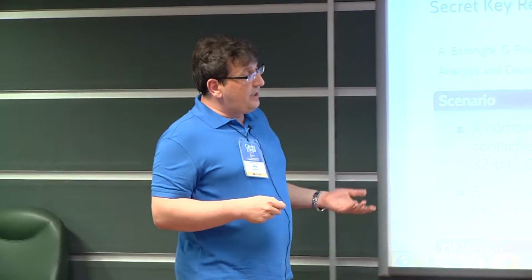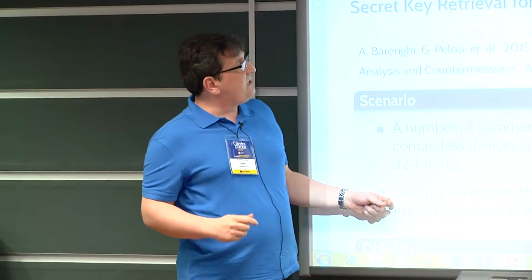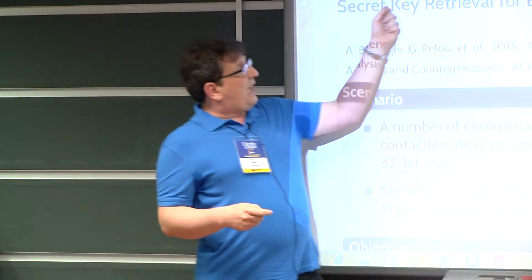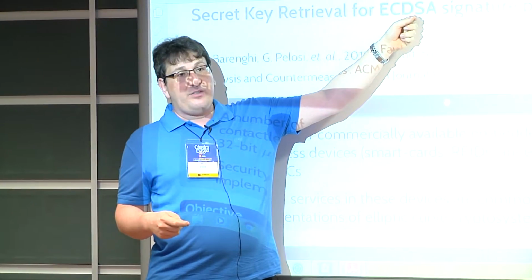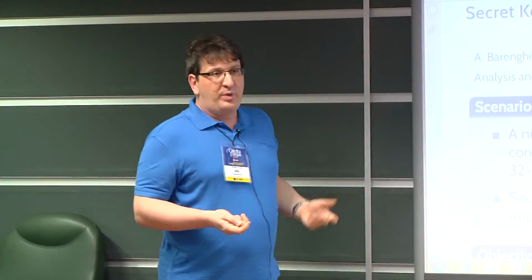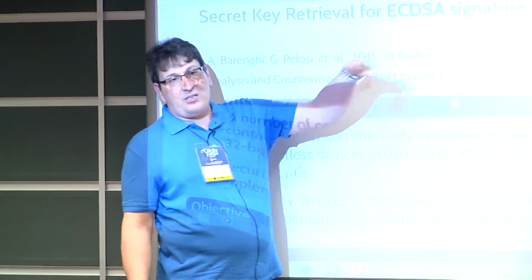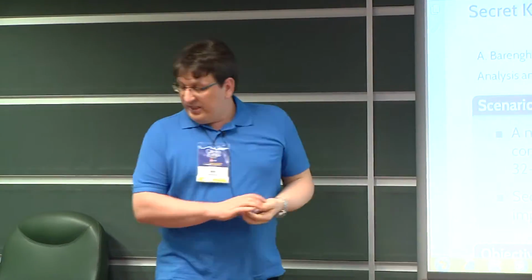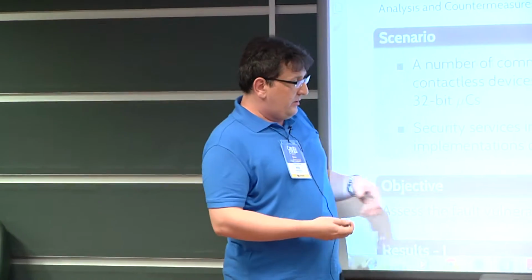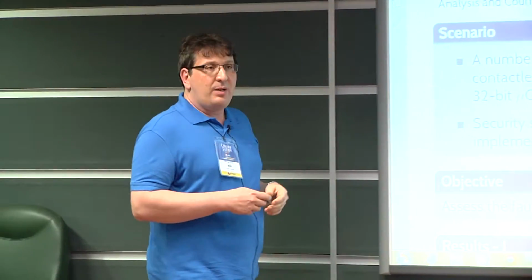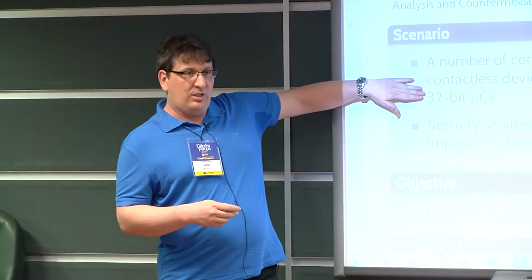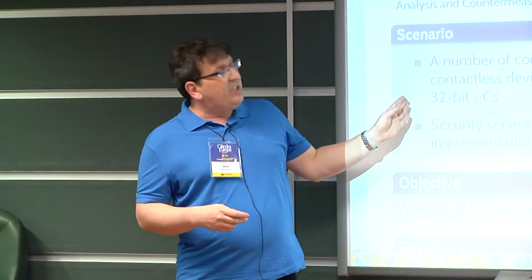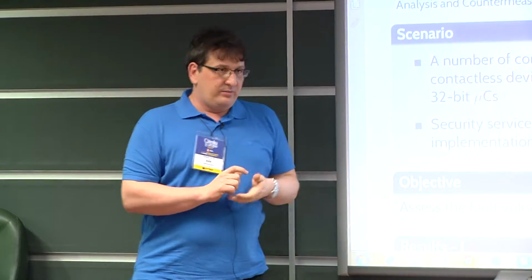And in particular, the security services on these devices consist of a digital signature realized through this kind of primitive. This is a standard digital signature primitive, the elliptic curve digital signature algorithm. So we decided to assess the fault vulnerability of the ECDSA software implementations on this kind of platform, on single-core microcontrollers with 8-bit, 16-bit, or 32-bit word length.